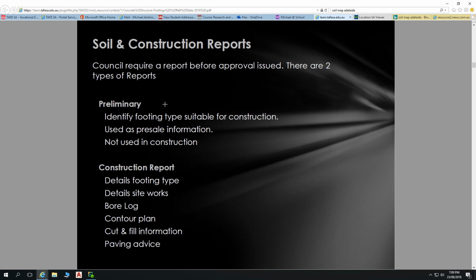We'll want to know about the depth of that fill as well, and whether that fill is the soil that was cut from there, and whether it was rock or not. Because if you've got some more friable rock that's broken out and laid down, and you've got a large excavator running around on top of that, compacting it as it's dumping more soil, you're going to get a lot of compaction, a fairly solid base under that. As opposed to if it's a very sandy soil that has been cut out and deposited there, you're not going to get a great deal of compaction. You're not going to get a great deal of strength underneath that.